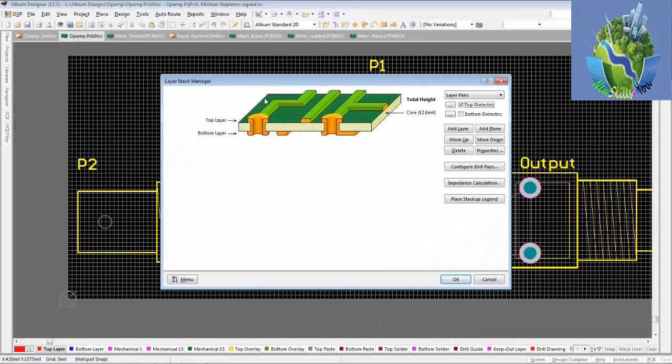I've now covered my copper and the fiberglass with a green layer that protects the metal except where I'm going to solder. Notice that these holes where parts go through, there's no green. This is called a dielectric layer. It protects your board. You've seen it on lots of boards. The ones from SparkFun are red. The standard color is green. I'm going to turn on my dielectric layer so I have them available when I ship my board off.